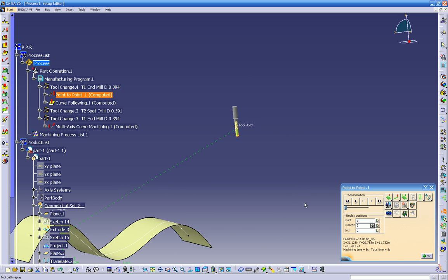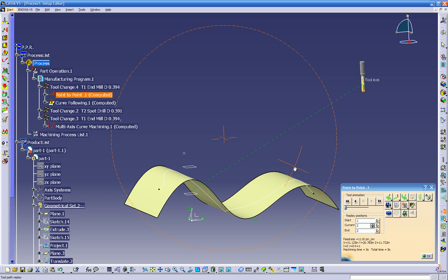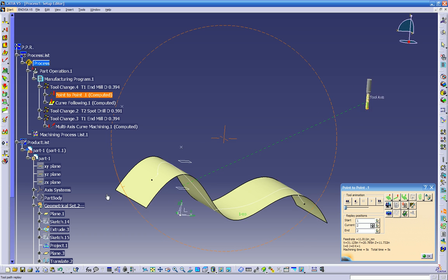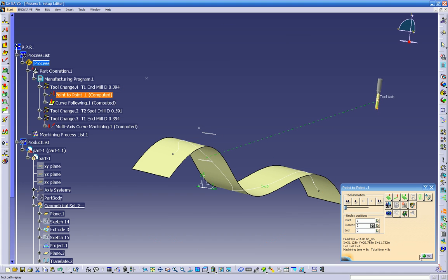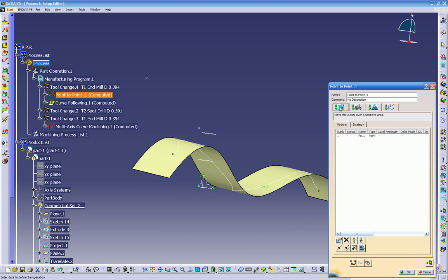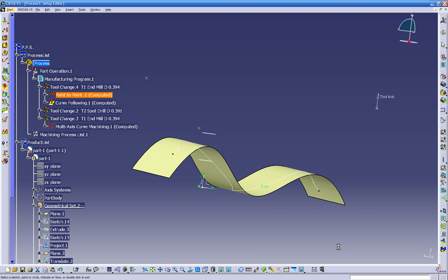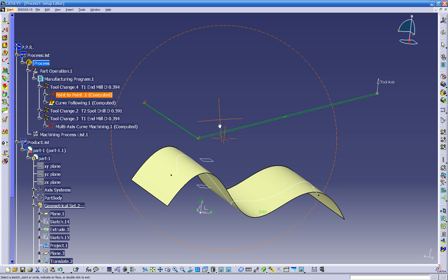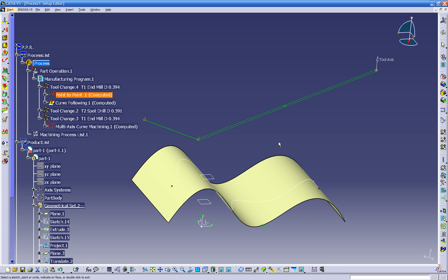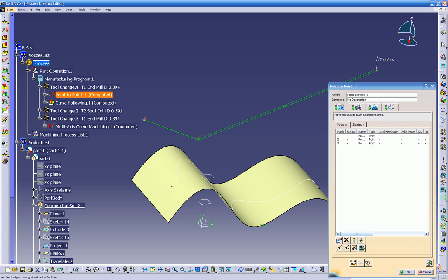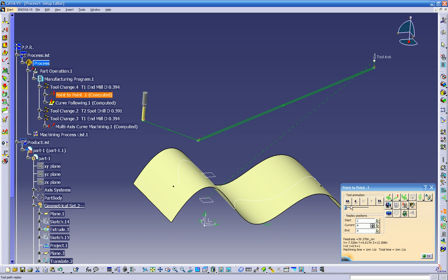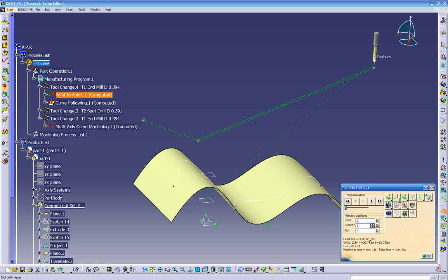So you can choose a couple points. I mean, you can have the tool coming over here, then over here, then over here to this point. It's totally up to you. You can choose as many points as you want. So go back to here and then choose this point option. Then go here. Double click, toolpath replay. And if you rewind, let's go step by step.